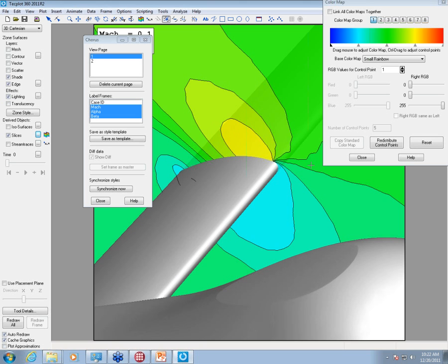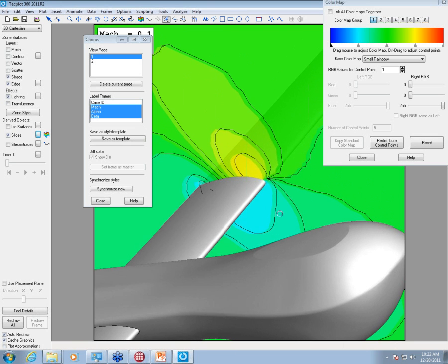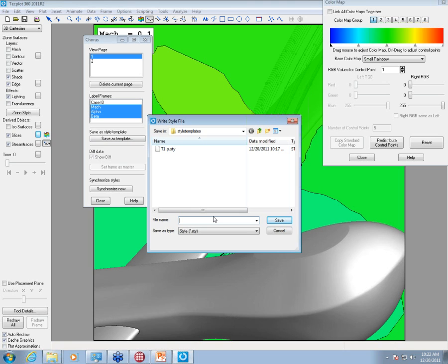So here we're going to look at some fine structure. I've just dropped in a slice. I'll zoom out a bit so we can see that. And one of the things I did was add some additional contour levels. So again, to see the variation in pressure coming off the wing, coming off the leading edge and trailing edge of the wing. And also for simplicity, I'm going to add, in this case, 10 stream traces, just to make sure that they look physically meaningful. Okay, so now we have yet another template. We can call this T2S for stream.